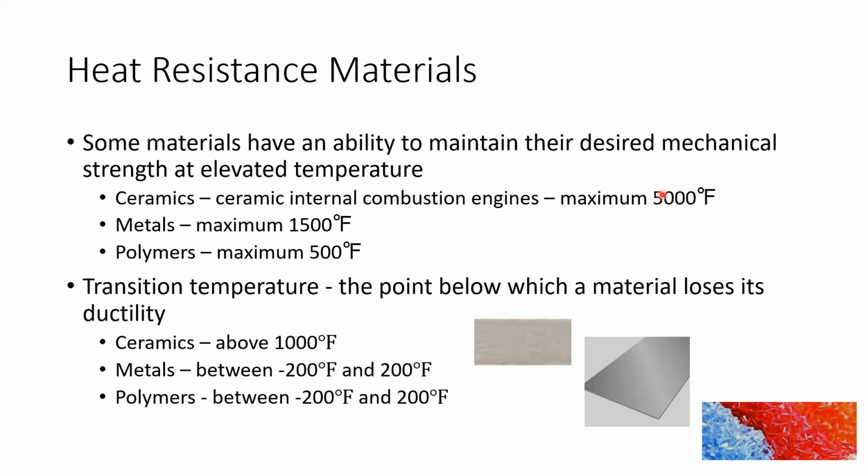They don't lose structure up to that temperature, but they lose their ability to stretch a little bit, like elastic, but not entirely lost, and lost the ductility. That kind of ability, you lose it up to that point. But they can maintain the mechanical strength up to this temperature. Ductility and mechanical strength are totally different things. You can draw the material to a certain point.